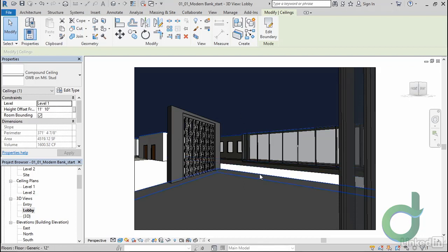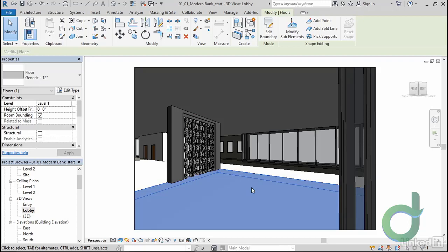We've started to break up the floor, and you can see I've got this one slab for my entry. Maybe that terrazzo will be here. And then I can put in other floor pieces around, where right now it's blank. When you're dealing with a model then, it's a good idea to really start to separate things out, even though there may be pieces that are contiguous, to really make a difference between your structure, i.e. the concrete floor slab, and the skin or floor that's going to go on it, the terrazzo, the carpet, whatever it's going to be. And to start to break things up for rendering a little bit will save you a lot of grief later on.